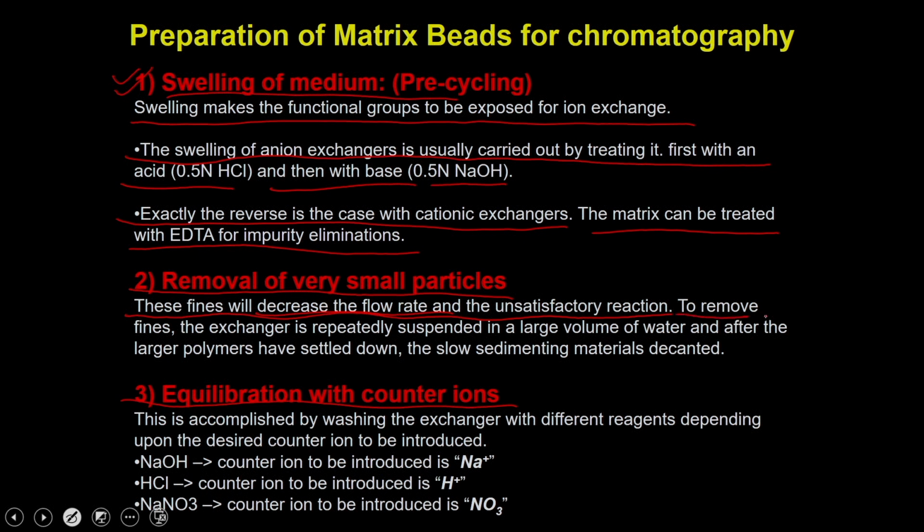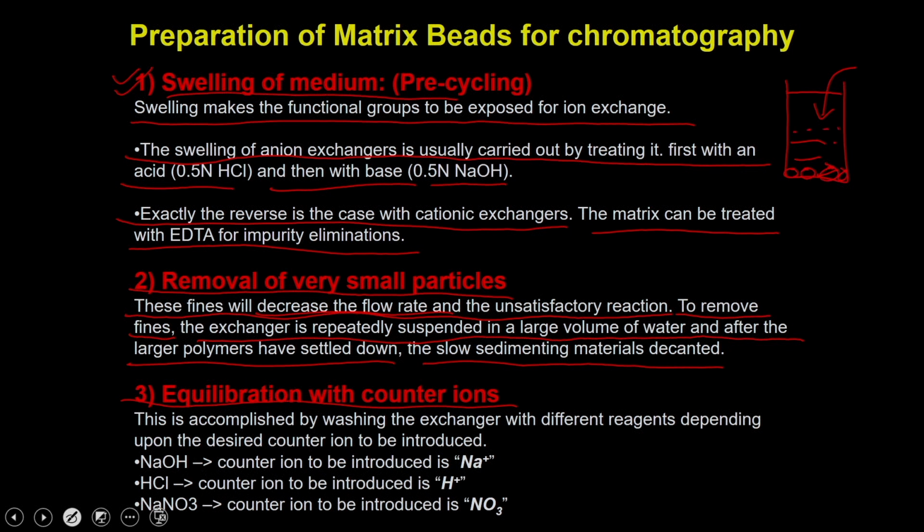So, to remove the fine particles, the exchanger is repeatedly suspended in a large volume of water, and after the larger polymers have settled down, the slowly sedimenting fines are decanted, which means you take the matrix into a beaker, okay, and then you fill it with a large quantity of water. Because these matrix particles are very heavy, they will settle down first, whereas the fine particles are going to remain in the solution.